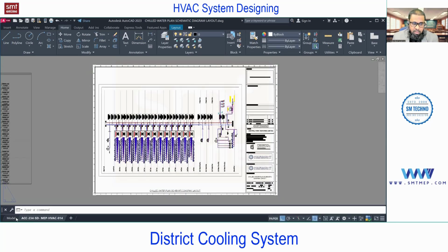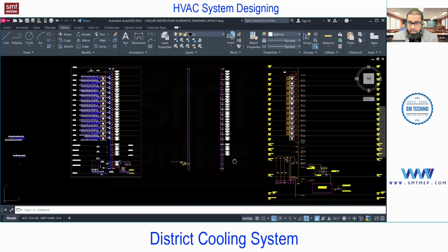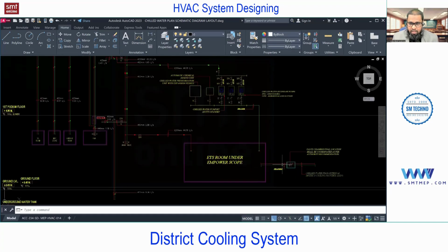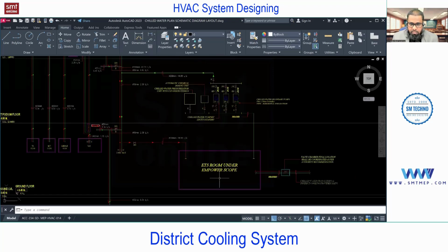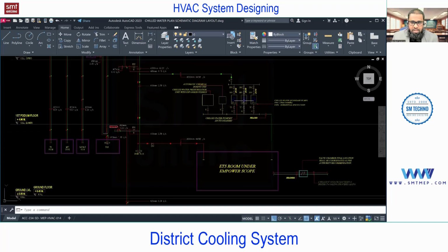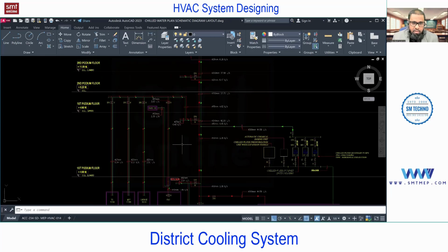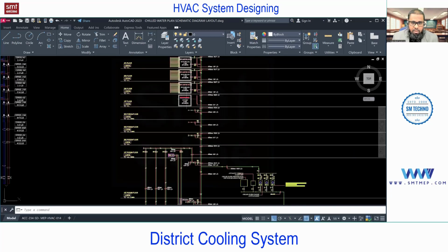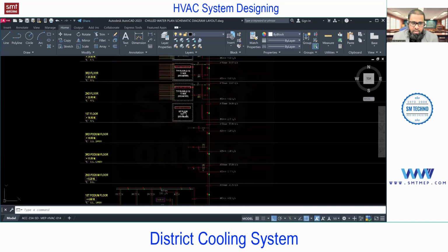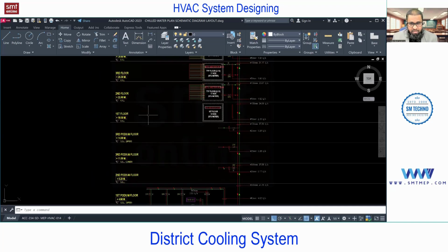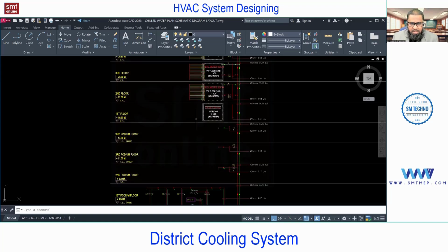In that you'll find the multiple electrical meters as per the apartment. Similarly, you'll find the BTU meter, and you see this is schematic, the supply of chill water from the cooling provider. Then it will connect to the secondary pumps, and it will enter into the different floors. Entering the floor, there's a BTU meter, 10 number of BTU meters. Assume that in this floor there are say 10 flats, so all 10 BTU meters and the supply to each and every flat. This is just for example.